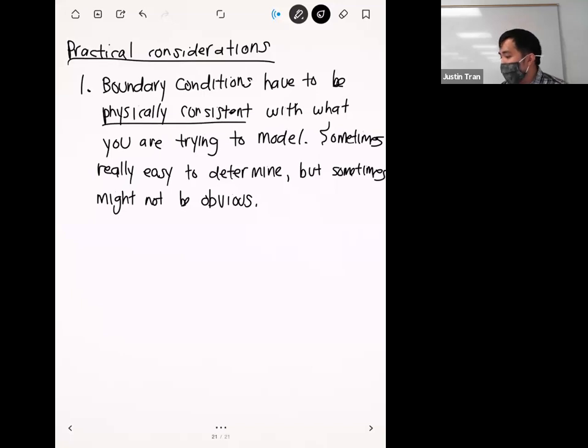And even when they're spread out, they're going to be applying force directly through their feet, right? And so it's not going to be like a flat thing. And so, should you apply the force as a distributed pressure force, or should you apply the force as individual point forces where each individual person is? Or should you apply it as pressures on the outlines of all their feet? It's not clear, right? It's not an obvious thing.